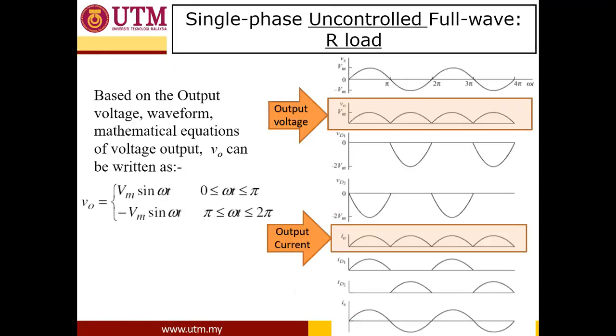So as you can see, the output voltage and the output current are the same as with the full bridge, because they are full wave rectifiers. But the difference is in the voltage blocking of the diodes D1 and D2. As you can see here, for diode D1, the voltage rating must be at least equal to twice the V input. Same with VD2.